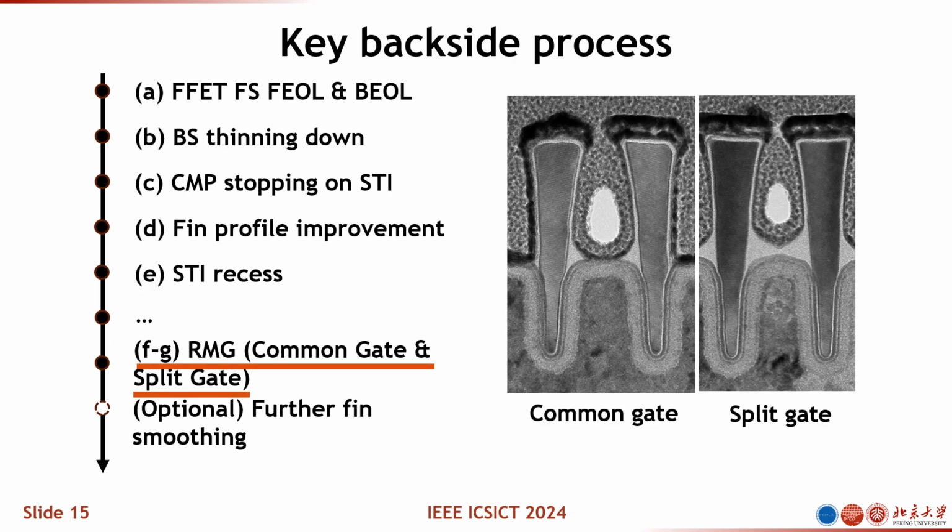So here, I show the results of the backside transistor formation, which is the cross-section of the gate region. You have the cross-section of the gates of the bottom and top transistors. And here, I also want to mention one critical benefit of the FlipFET because of the split gate. The split gate actually is a very important technology enablement element for the standard CMOS. And this split gate concept is very important for sequential logic, and I will talk about this in detail later.